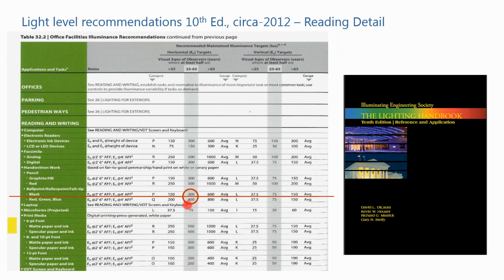So that's the bad news. The good news is that it's easy to convert from lux to foot candles. 300 lux is about 30-foot candles. So it's 10 to 1. If you're really wanting to get exact, it's not exactly 10 to 1, so you'd want to do a calculation, but for the most part, we're looking at 30 to 40-foot candles here, and that's certainly what we typically see in a lot of offices. 35 is often a target that we're using.